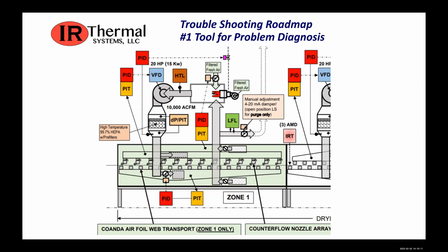Because once again, we're putting more air into this dryer box than we're pulling out by the manual positions of those. During commissioning of a dryer, we would manually balance the entire system, and we'd usually scribe, mark, and document where they were sitting, so it'd be easy to identify if these were in fact changed. If they were, then my guess would be that we have some sort of clog, and visually inspect and find where that clog would be.